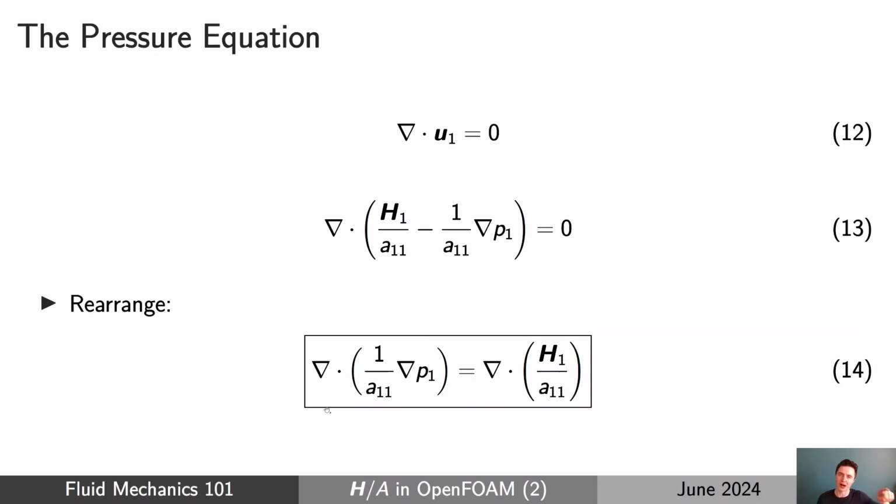Every time we go round the loop of our SIMPLE or PIMPLE or PISO algorithm, the actual pressure equation that we solve is different every time, and it's implicitly linked with the momentum equation that we've just solved. So that's also something new which you may not have thought about before. The actual equation that we're solving is different and changes each iteration.